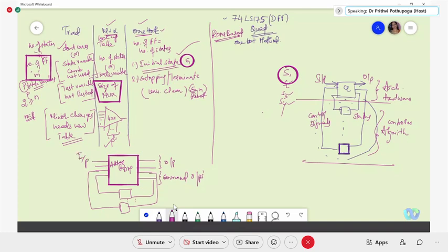It is the same thing, but here in place of this combinational logic, we are trying to use a ROM wherein the address is defined by the combination of the inputs and the status variables. This along with your input and the status signals will define the address of the output. That defines your total output of the system.